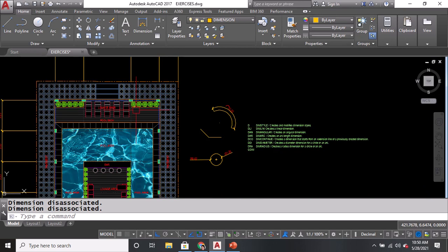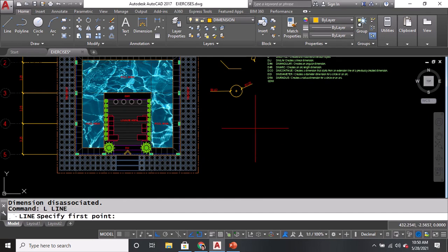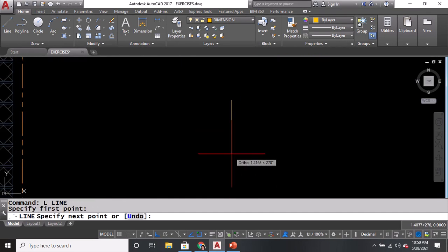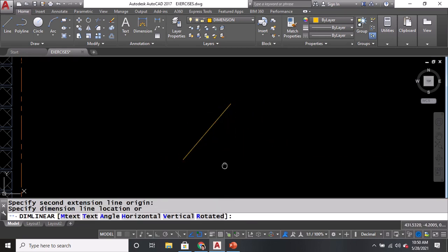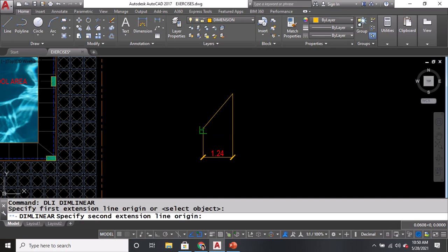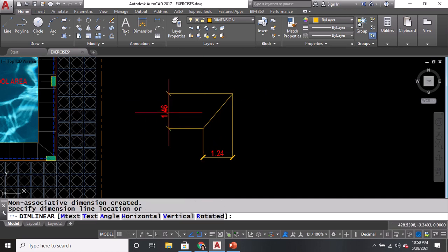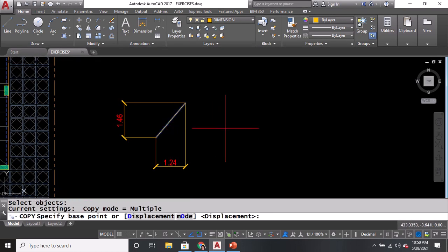And last one, before I leave everything, let's see. Going to create a line. I need a, there you go. I'm going to command for DLI, 1 and 2. So, it gave linear. Okay, linear dimension which is X or Y only, or vertical. So, let's try again. DLI, 1 and 2. There you go. Okay? But what about, sorry, what about align?